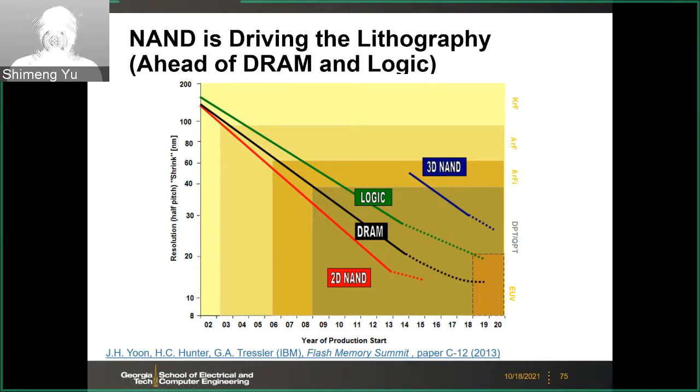Because in the NAND flash, the pitch between word lines is the smallest feature you can fabricate on the chip, and it is actually smaller than the logic design rule in the SRAM and so on. So the NAND flash has the highest density in terms of feature size. The NAND flash really pushed for the scaling of the feature size, till around 2013-14, when it approached around 15 nanometer, or 14 nanometer.